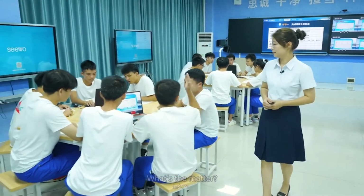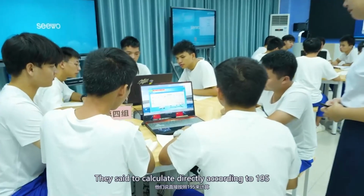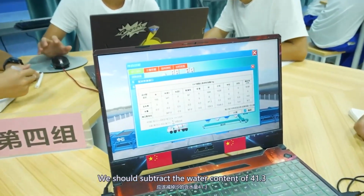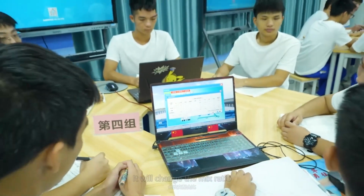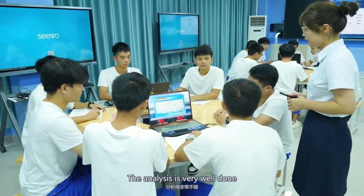Teacher, our group has different opinions about the water usage. They said to calculate directly according to 195, but I think we should subtract the water content of 41.3. Because the site uses gravel that contains water. If we don't consider such moisture content, it will change the mix ratio, thus affecting the strength of the concrete. The analysis is very well done.